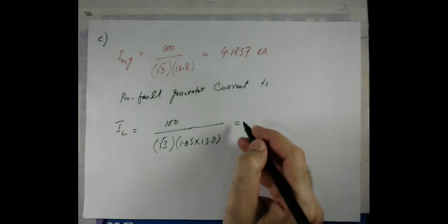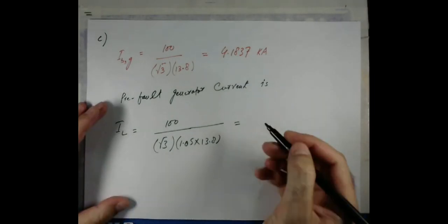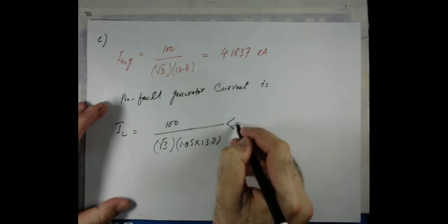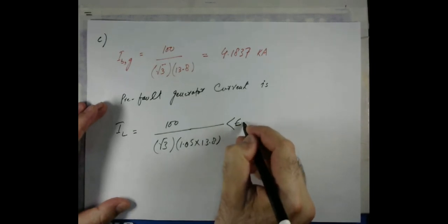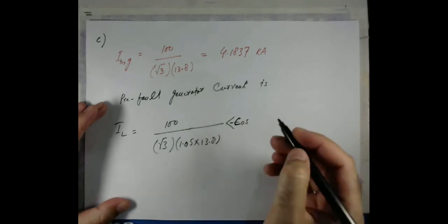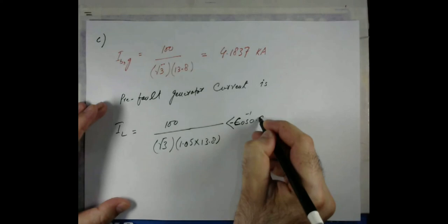The power factor is given, which is 0.95, and if I take the cos inverse of this value, I will get the angle. So I also have to consider this value. Let me now take the angle. That will become minus the cos inverse of 0.95.